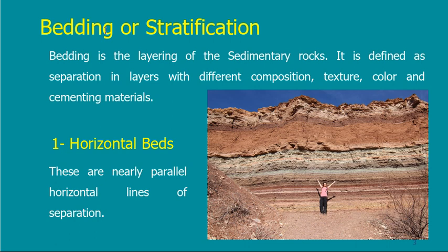During this period of time, soil was sedimented in a different way. Then later, time changes, and the type of formation has changed. So another new type of layer starts to sediment at this location, so there will be a separation line. So if I look here, I will find lots of lines. All of these lines are called bedding.